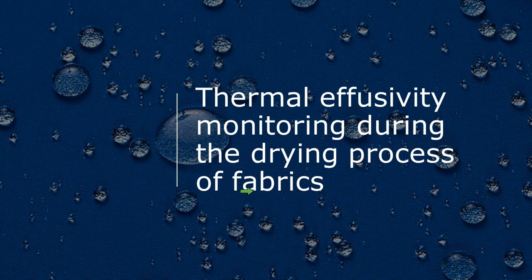But I wanted to share some illustration as to the potential of this to look at some really interesting situations where we've got moisture added to a textile. It's a very dynamic event when you add moisture to a textile. So normally when we do a dry material test, we're typically taking 5 measurements and taking the average of them, and usually we get an RSD, a relative standard deviation on those measurements of around 1%. So it's very consistent, very precise in the measurement.